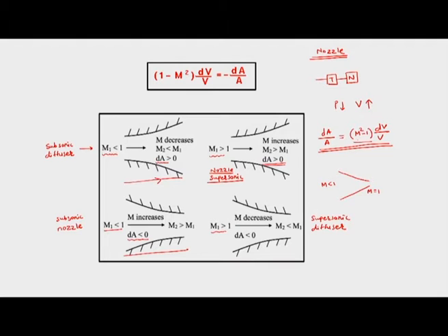Then from there we add a supersonic nozzle, where Mach number is more than 1. So, we can go from subsonic to supersonic Mach number in a nozzle if we have convergent and divergent sections together. In that case, it is called a CD nozzle.